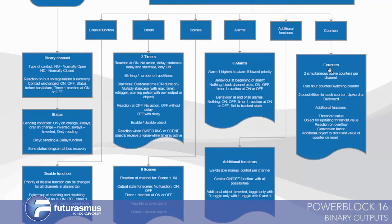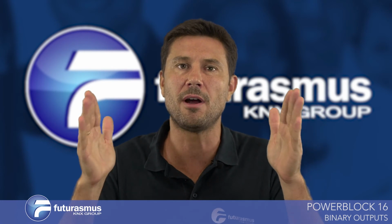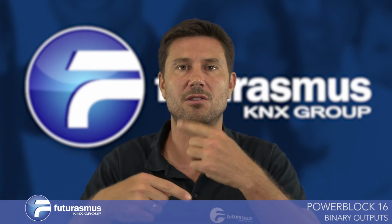And then, for me, also a very important function linked to the channel are the counters. So there are 2 counters which can work simultaneously. One can be used, for instance, as a run hour counter. So you can count the time the relay is closed, so that you can know how many run hours have passed for this load. You can even set it to count down. You can decide to count up, or you can decide to count down.